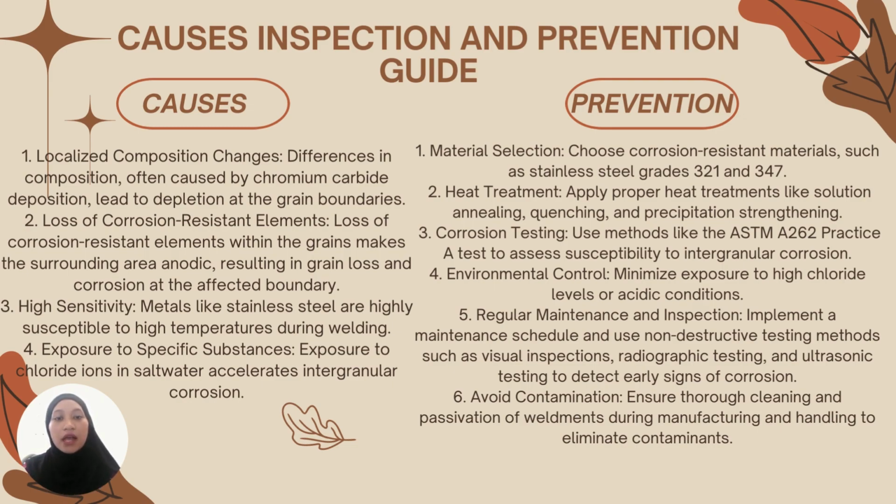High sensitivity also affects, for example, metals such as stainless steel, which are very exposed to high temperatures during welding, and exposure to chloride ions in salt water can also accelerate intergranular corrosion.